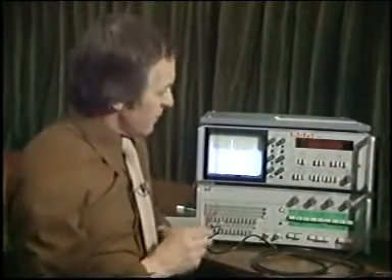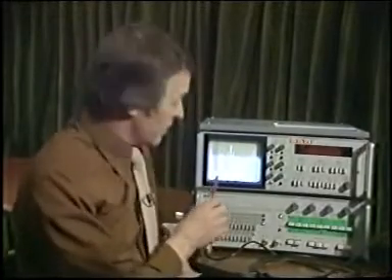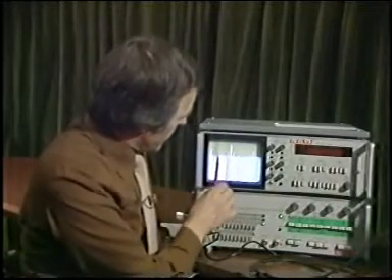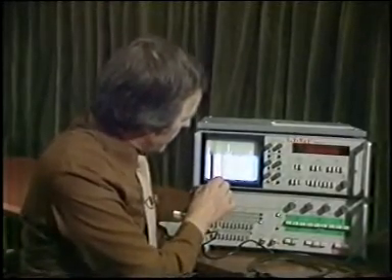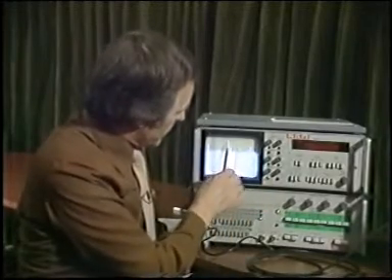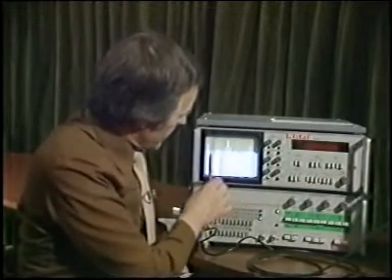So, how do we go about recovering it? Well, the obvious thing to start with, in this situation, is to try to filter out all the components that we don't want. In other words, we put a low-pass filter in which will take out all the components above there. So we hope it will take out these interfering components and also all these other components.